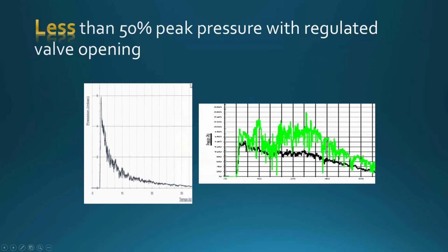Now the other thing that you're quite likely to come across dealing with inerts is what I call pressure regulating valves, and all of the main manufacturers have them now. We did have the opportunity to test one during our experiments, and found that they produce roughly about half the peak pressure that would be achieved with a normal inert gas discharge, which really makes a huge difference in terms of how much venting is required and how tight the enclosures have to be, and so on.